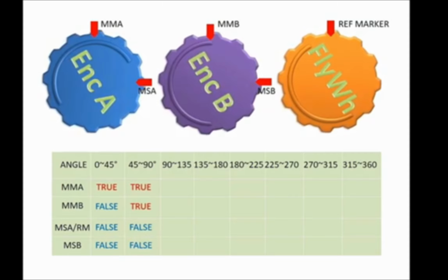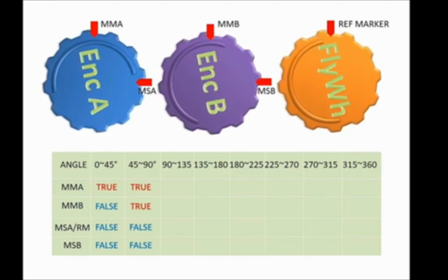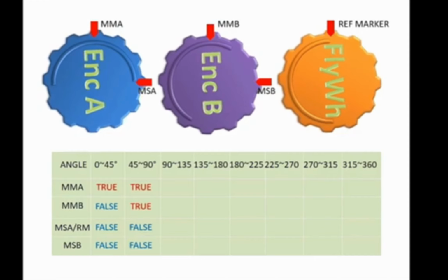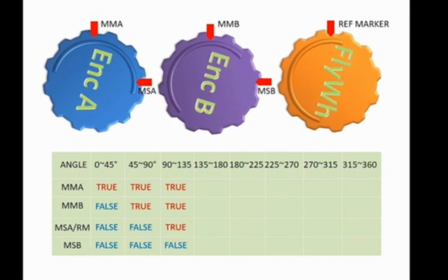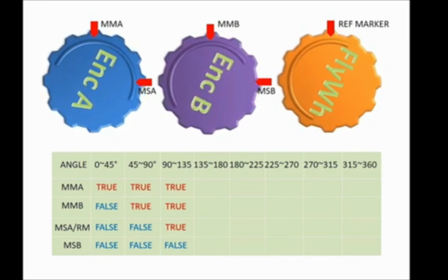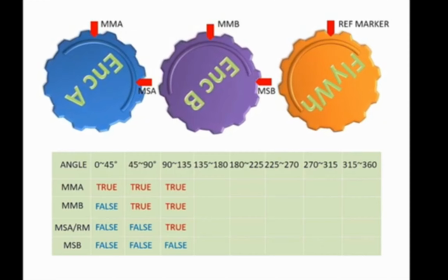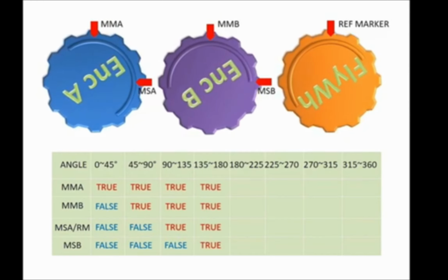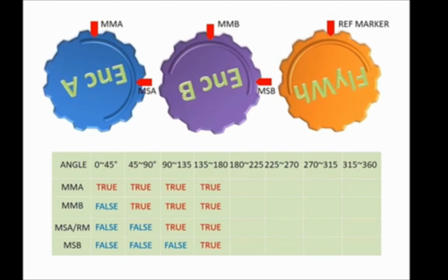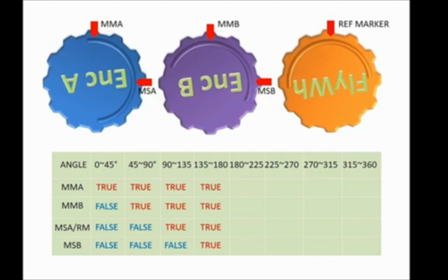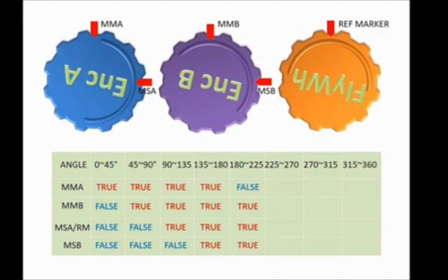This animation will show you in each position the status of all 4 sensors in the tabular column. With this we can determine which 45 degree position the engine is now in, so that the unit starting valve will start for the initial movement. Once one revolution is achieved, the whole system will get reset with that actual position. After that the computer will calculate the correct angle, and all the system will continue to run.